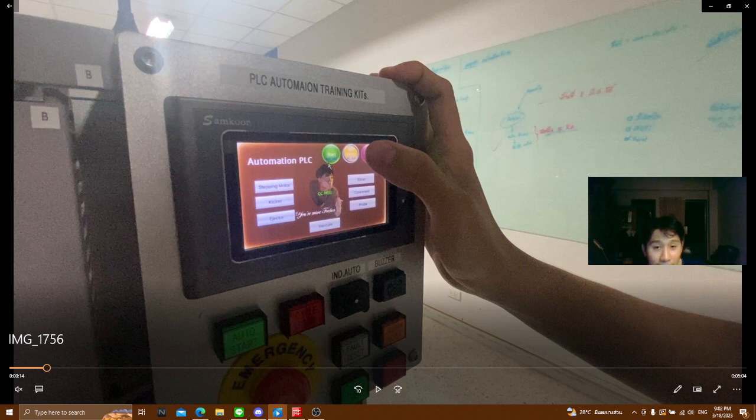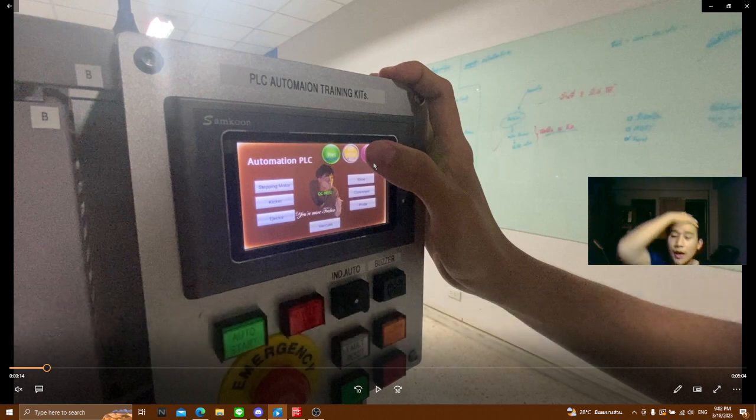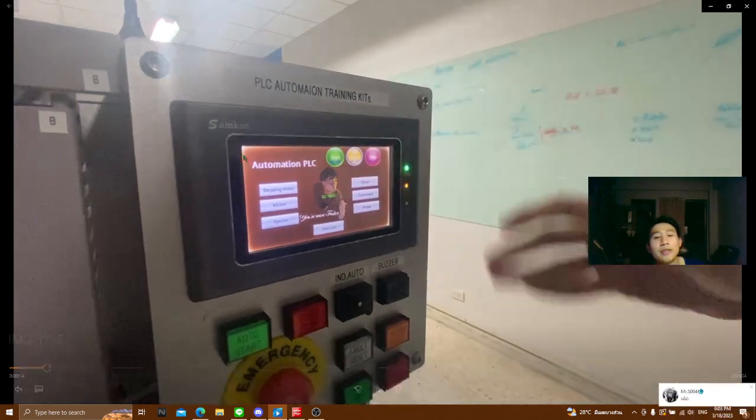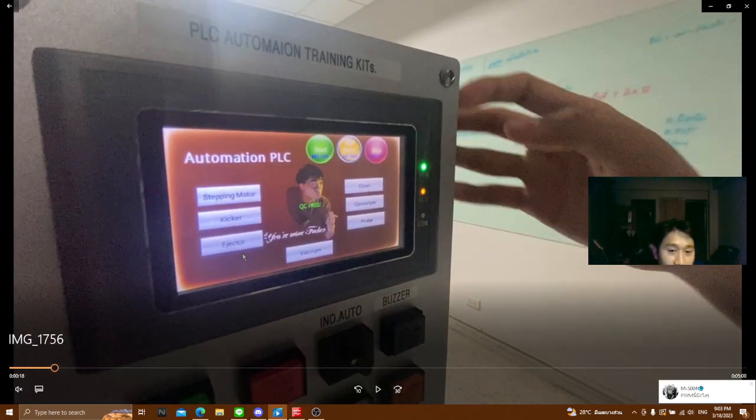And this is our monitor, which has a start button, reset button, and also a stop button. The reset button we created is in addition to the component commands, because sometimes an error happens and we need to reset all the values. By pushing the stop button, which is self-holding, we need to cancel it by clicking the start button. But if we click the start button, the slicer will activate. So we create one button which is reset. It resets the value of the second stop button, but does not start M0. And then we create the step motor, slicer control, kicker, conveyor, ejector, probe, and vacuum.